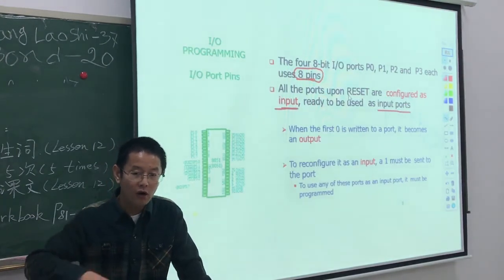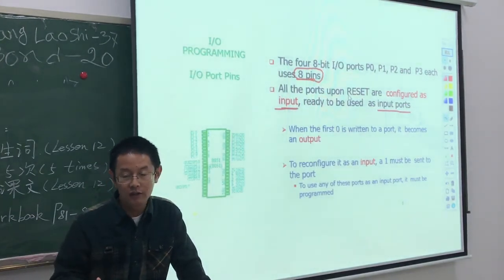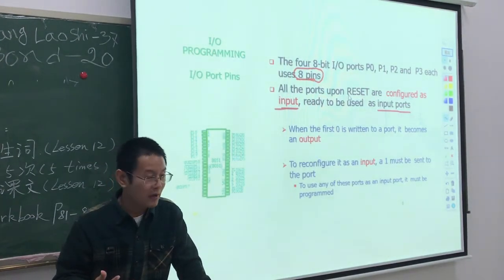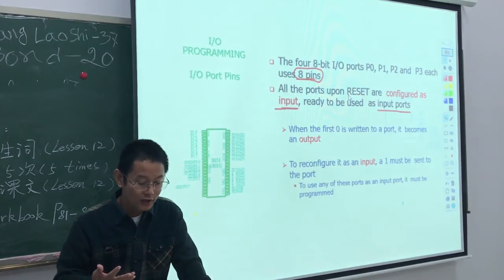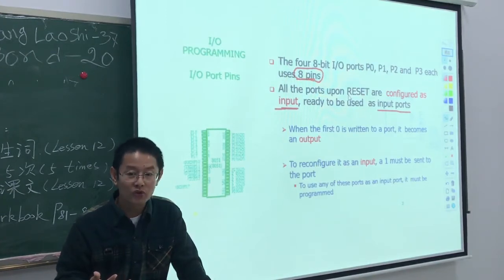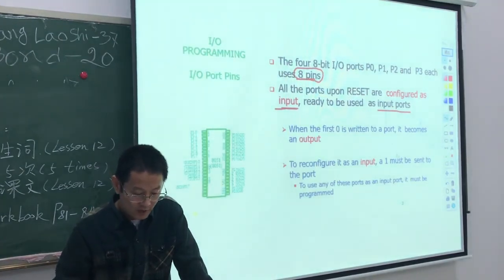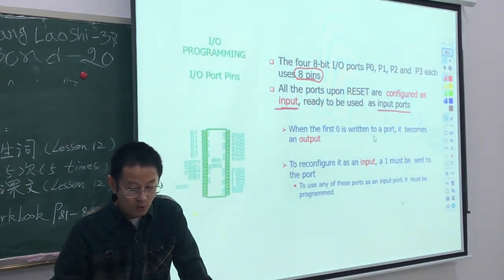When you power on the microcontroller, the ports are configured as input ports. When the first 0 is written to the port, it becomes an output.